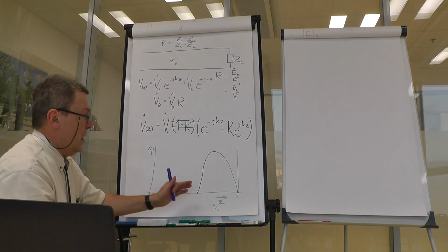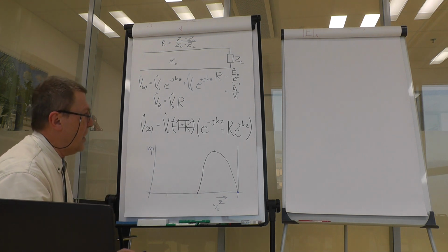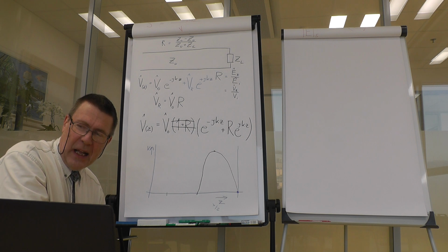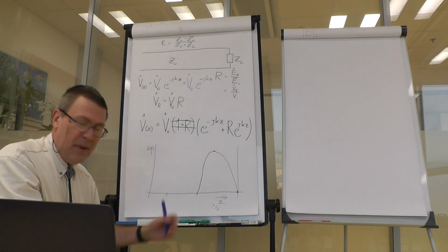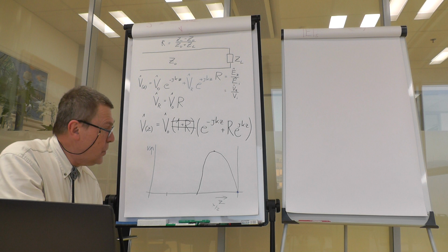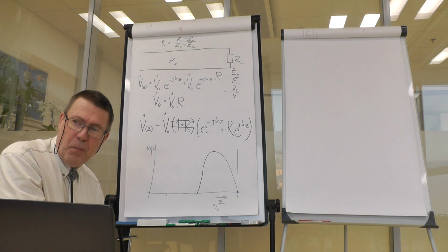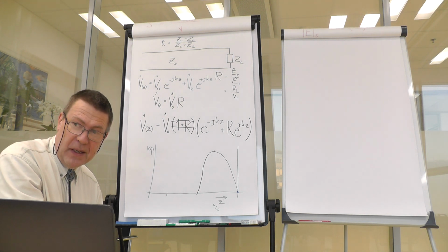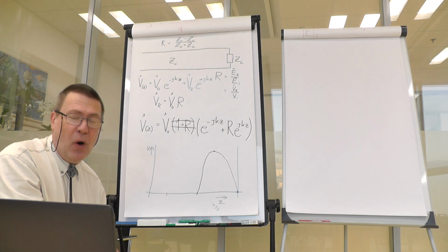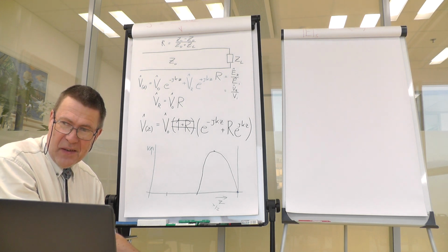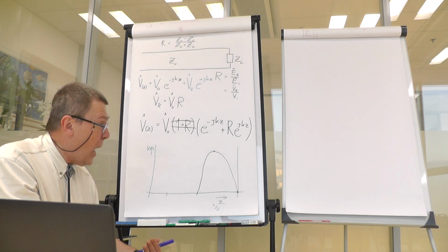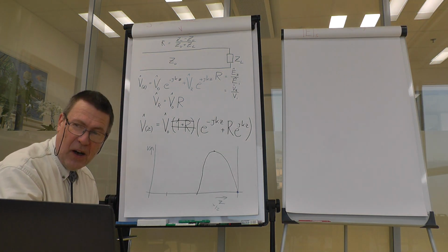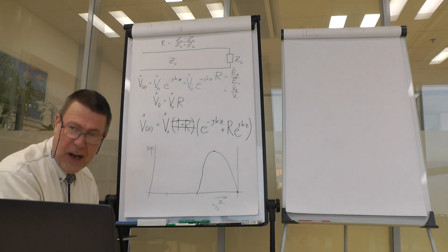Now, this is not very useful if you have a transmission line and you would put there a thing like this. You would encounter that there is no real propagating power. If you average the propagating power over a long time or over one period, you will get 0. Why? Well, just remember, we have had the reflection of magnetic field which was in phase.